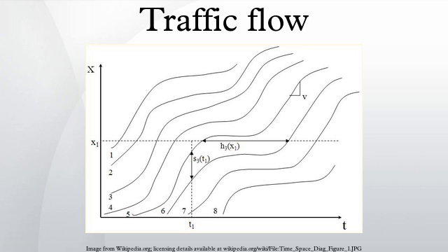This model implies that the users later on in time will take longer to accelerate as they meet each of the lines. Instead, a better approximation is a triangular diagram where the traffic increases abruptly, as it would when a driver sees an opening in front of them.